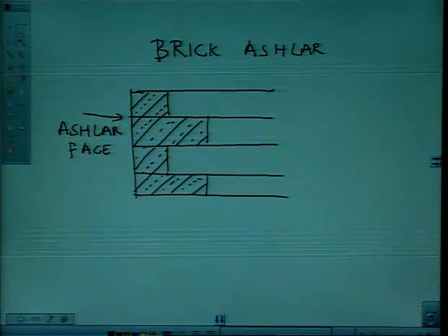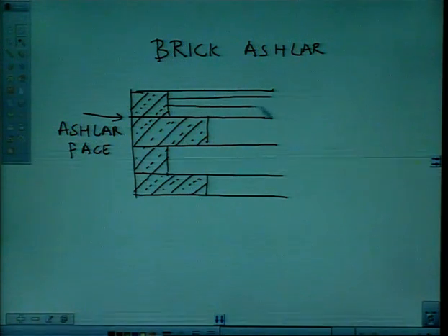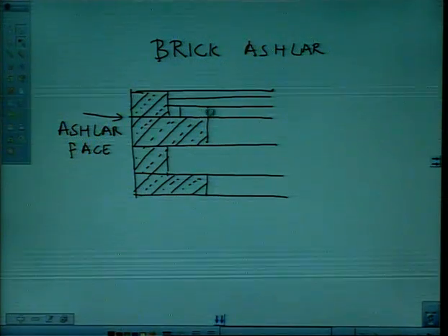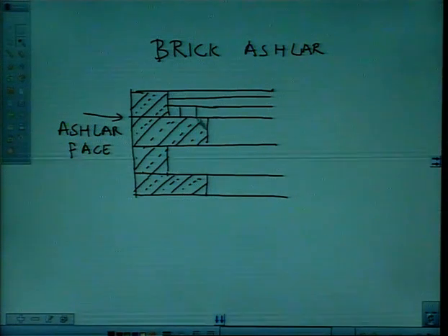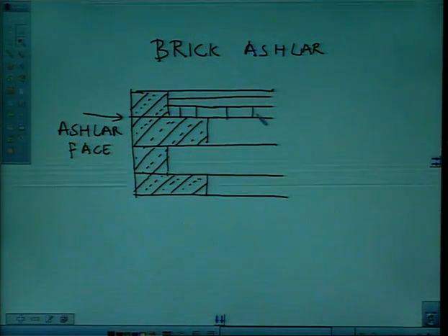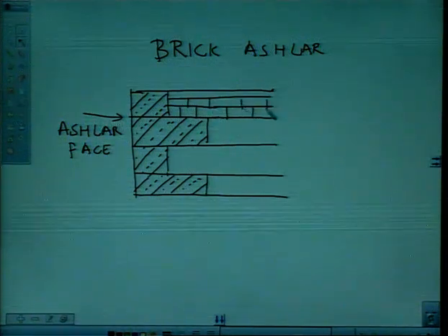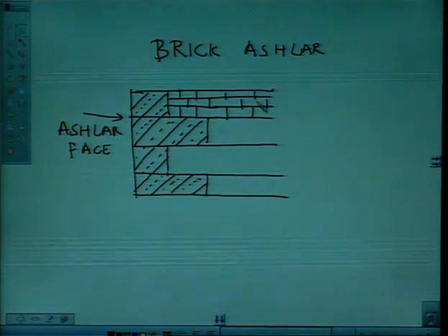And the backing is brick. Bricks are of smaller size. Joints should not be continued. So, breaking of joints should be there. This should be kept in mind while arranging the bricks, and it should be checked.